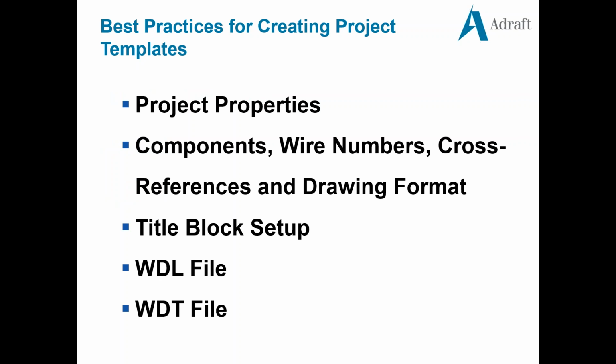So some of the best practices for creating project templates are the project properties. Very, very important when creating template projects. It's extremely important that you get all your company standards. When I talk standards, I mean properties inside of the software itself. And that can consist of your component, your wire numbers, your cross-reference, your drawing format.